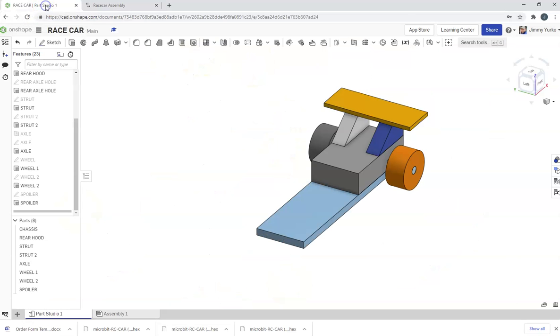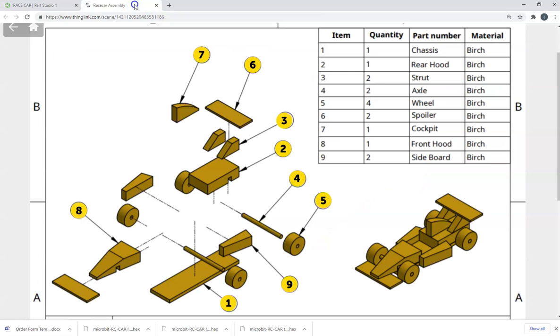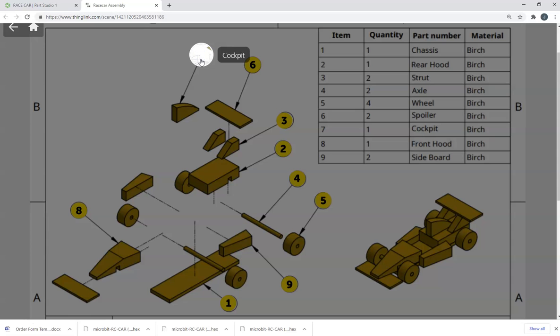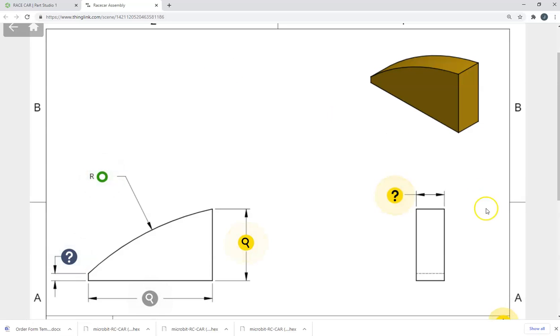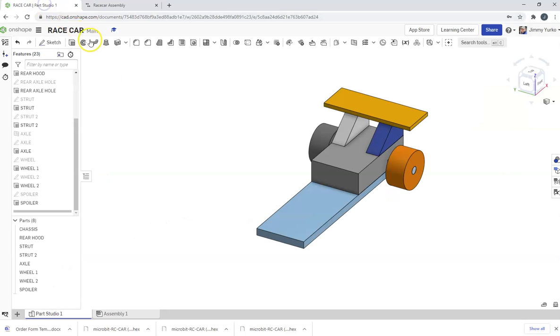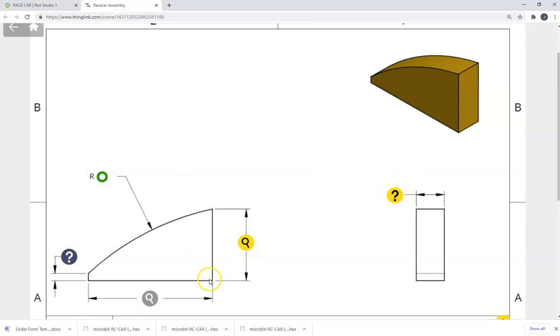First, let's go ahead and check out the sketch in the drawings. The drawing tells us what the exact profile of the object is. And we can see in the right side view that it's a uniform thickness, so it's just going to be a matter of drawing the shape and extruding it. You can see that there are 3 straight line segments and 1 arch. And also that the angles between the line segments are 90 degrees.